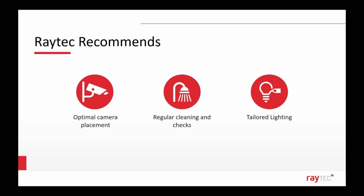A 25 to 35 degree angle from retroreflective plates. It doesn't matter as much for non-retroreflective plates, though the effect on your analytics in order to identify characters has to be considered. We also briefly touched on the ability to move your lighting away from your camera, but with the caveat that it needs to be on the same axis in order for the light to bounce off a plate and back into your camera.